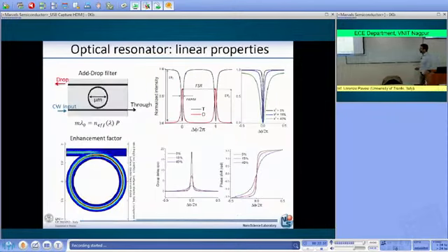So now I hope that you have got the meaning of the microring resonator. This is an add-drop filter. Typically we have an input port, a through port, and a drop port. The resonance condition is given by the physical length of the microring resonator, multiplied by the effective index of the silicon core waveguide. And this gives you the resonance condition.